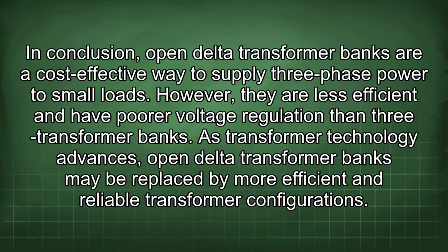In conclusion, open delta transformer banks are a cost-effective way to supply three-phase power to small loads. However, they are less efficient and have poorer voltage regulation than three transformer banks. As transformer technology advances, open delta transformer banks may be replaced by more efficient and reliable transformer configurations.